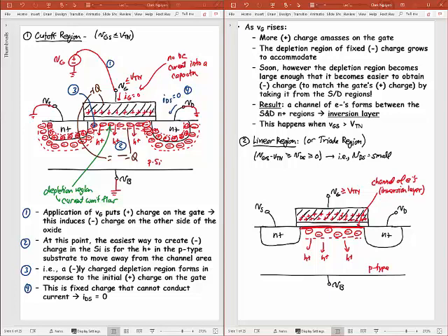And so basically, I still have these depletion regions here around all these things. Right, I still have my negative charge that's happening because I have PN junctions around my source and drain here. Still have that negative charge, but the more interesting thing is definitely the fact that I have this inversion charge.